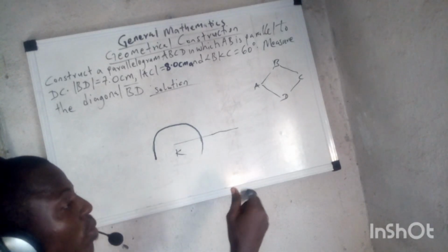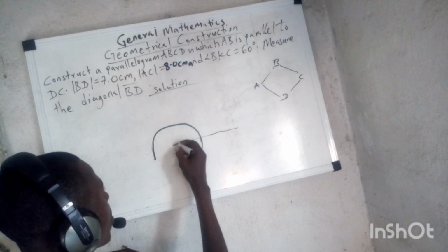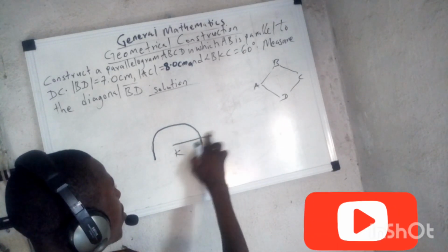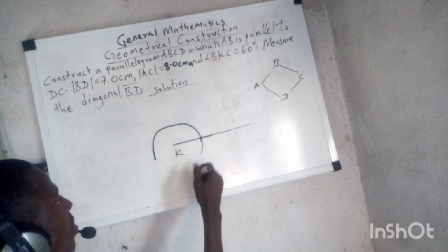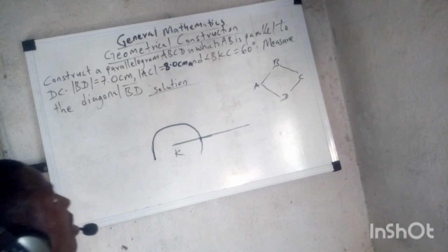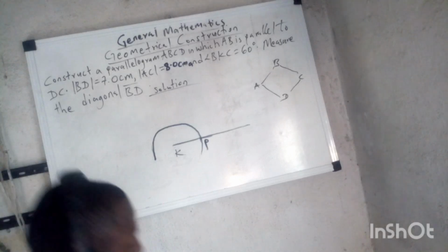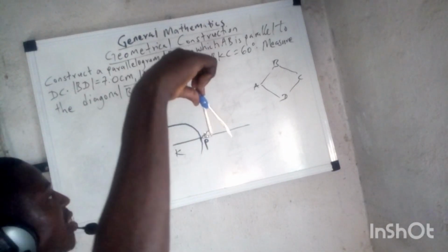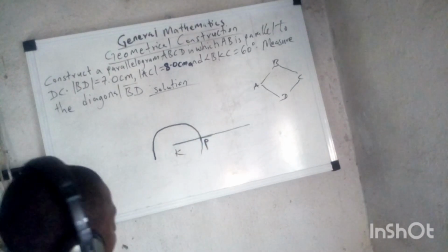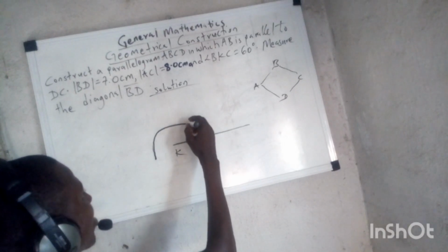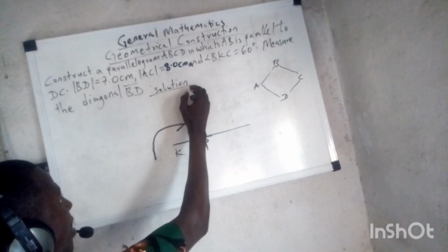Don't forget your pencil must be properly sharpened. You inscribe an arc at the point of intersection. Your lines must be visible. At the point of intersection, you can also name it. Let's name it P. Also, you bring out your compass again, and take P as your center. Having done that, with P as your center, you then bisect the arc.